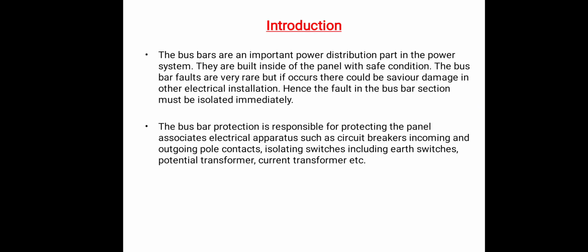Now let us start with some introduction of busbar. The busbars in electric power stations and substations are one of the most vital elements. Although with the advent of modern design methods, the probability of occurrence of a fault has been reduced to negligible, if a fault occurs on a busbar, considerable damage and disruption of supply will occur unless some form of quick acting automatic protection is provided for isolation of the faulty busbar.